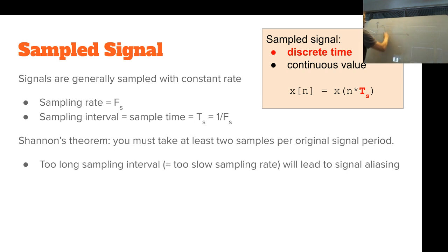Okay, if you have a sine like that, think of how many samples you must have to show this one. Well, I would say 1 here, another here would give me a good picture. And if you have fewer samples than that, then you do not see the big picture anymore. For example, here 1, but then another one would be, in the worst case, here. So then it looks like that kind of signal, compared to this, where if you have at least twice, it already starts to look like a periodic signal.